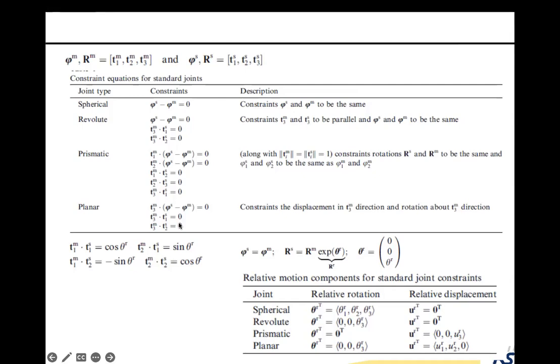But we also did a slightly different approach with one of my students. We implemented the so-called relative motion approach, where on top of your beam, you add the ability to handle a local equation. For example, if you talk about a spherical joint, you already enforce that all displacements are the same. You can only have the 3 components of relative rotation. So you can have one node be a master, the other one a slave, and the motion of the slave is expressed with the global motion of the master plus the 3 relative rotations.